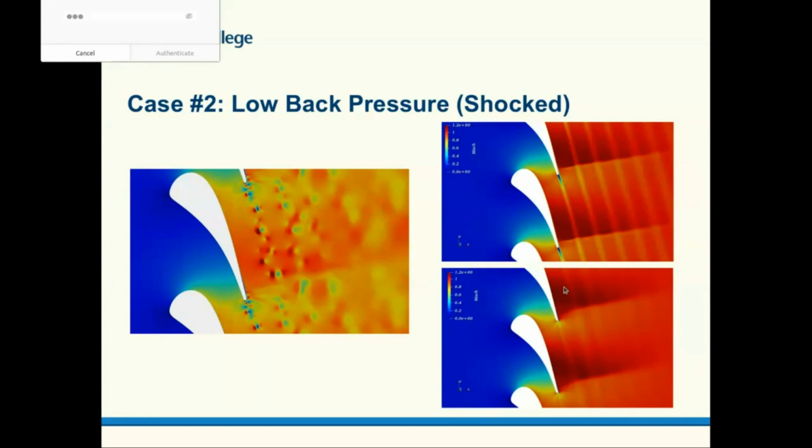in quite an aggressive manner. And then of course the wake propagation being pretty uniform in the case of the RANS, whilst in the case of the instantaneous time average solutions it's less so, because these vortices are not at every location at every time step, but sort of propagate throughout the domain, so you're going to get a void and therefore get less dissipation than what the RANS predict.